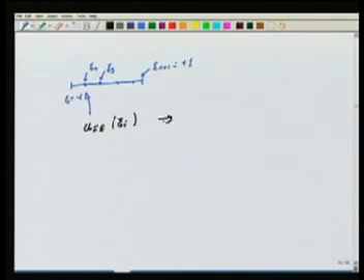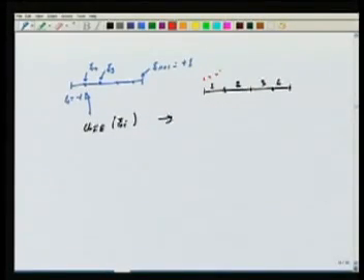These I can output, so I can loop element by element, that is I go over the various elements in the domain, element 1, 2, 3 and 4, and for each element put this uniformly distributed set of points, output the value of the displacement and the derivatives at this point. So let us say I get something like this as my output. Okay. So now I can connect these by a line to get a plot of what my finite element solution will look like over the whole domain. This is it. So as far as plotting is concerned, I can output the values of the finite element solution at these points, connect them by a curve, and I am done. Similarly, I can do the same thing for the derivative.